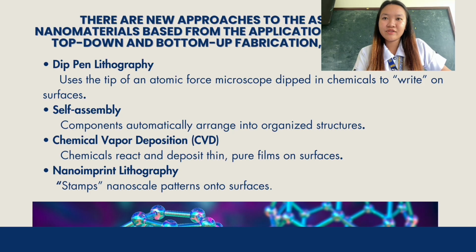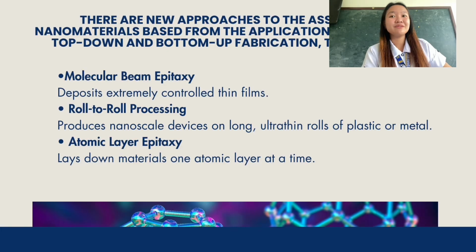Last one, we have atomic layer epitaxy. It lays down materials one atomic layer at a time. Each layer is added slowly and evenly, ensuring perfect uniformity. This is ideal for microchips, batteries, and optical devices where thickness must be exact.